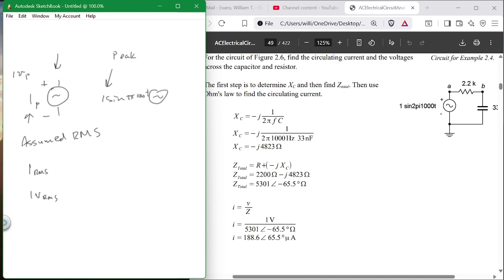So what would be the value of I? Okay, so now we're down to having to calculate all this stuff and then find, like we did before, I equals V over, it used to be R, now it's Z. This is our Z, this is our total impedance or resistance of the whole circuit, right? So how do you do that? Well, it's a two-step operation. First of all, you've got to calculate these resistances.